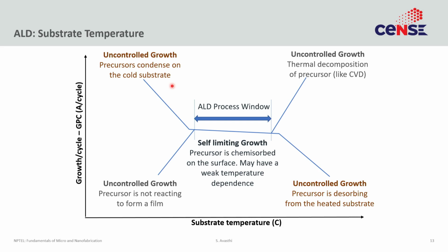Imagine this is what would happen if you cool the wafer and you are letting in water, right. So, if you are cooling the wafer and you are letting in water, there is a possibility the water will just condense on top and form a film, just like mist condenses in the winter morning on top of leaves, right. So, if that happens, then this is not adsorbed or chemisorbed water on the surface, right. This is just condensed water on the surface.